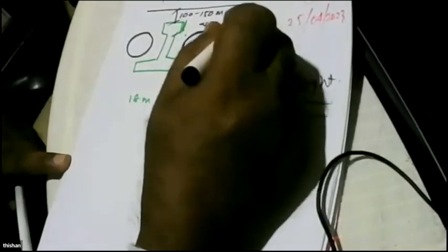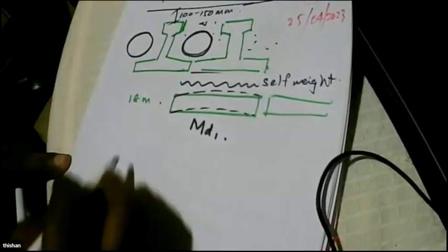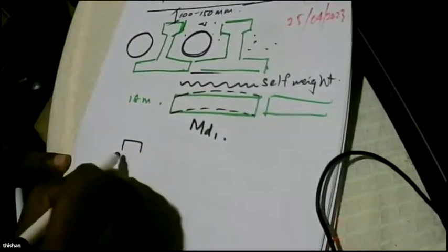To reduce the weight, you can even use polythene filled up with sawdust as a void form. But the density of concrete is very high, and it's very difficult to control this void form. Because of that reason, it's not popular at all. So people like it this way. So what happens is you get a beam.